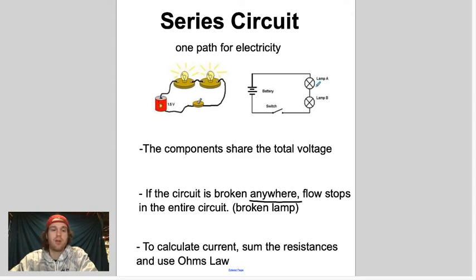They can be in parallel as well. It just depends. Actually, your lights in your room are not in series. They're definitely in parallel because if one burns out, they don't all burn out. We stopped wiring in series a long time ago for most things. However, you can use wiring in series to protect certain circuits in your home, stuff like that.